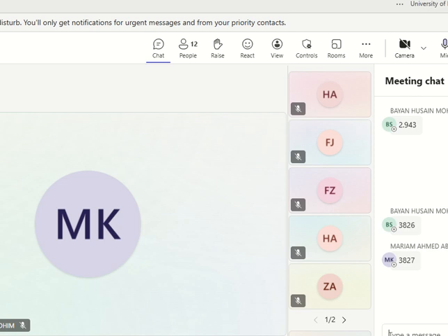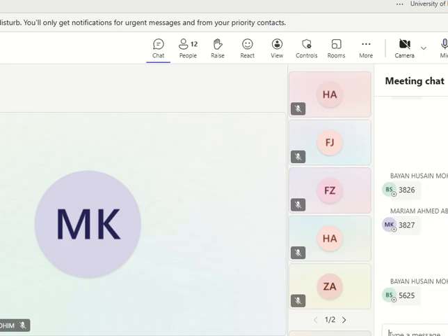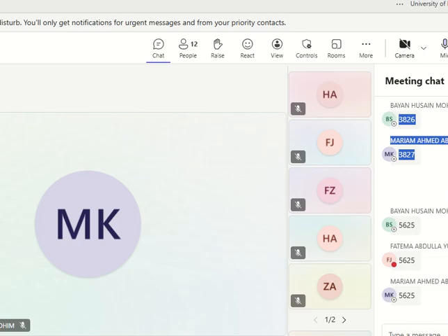How much if we didn't do this conversion factor? So now imagine 5,600 and the actual answer is 3,800. Imagine the difference. It's almost the entire capacity of a lane. You are missing an entire lane here, or you are over counting an entire lane.